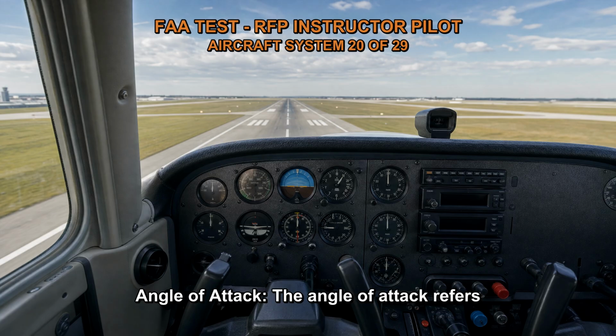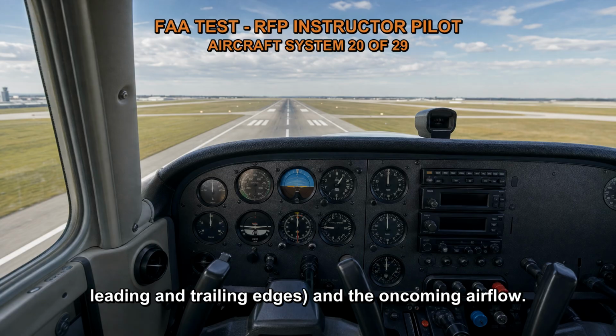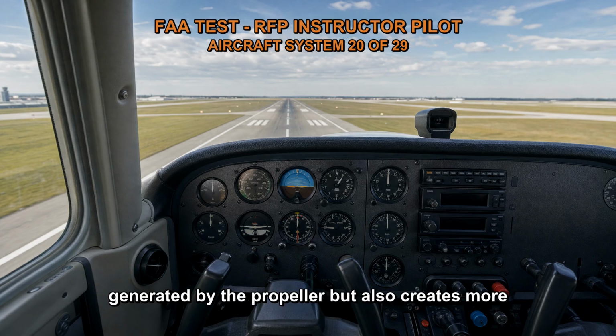Angle of attack. The angle of attack refers to the angle between the chord line of the propeller blade, the straight line connecting the leading and trailing edges, and the oncoming airflow. A larger angle of attack increases the lift generated by the propeller, but also creates more drag.